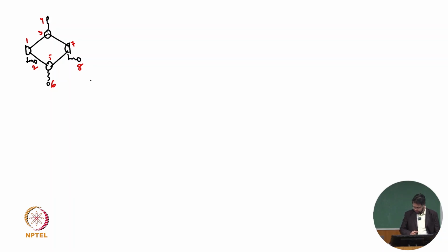Okay. So our first target is to write the dynamic stiffness matrix of that full thing. How can we write the dynamic stiffness matrix? That is K minus m omega square plus L. Okay. So what is in the K?